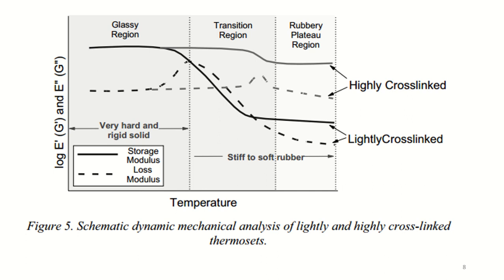A glass transition region, where the storage modulus can decrease by a factor of 10 to 100, and the loss modulus and tan delta reach maxima.